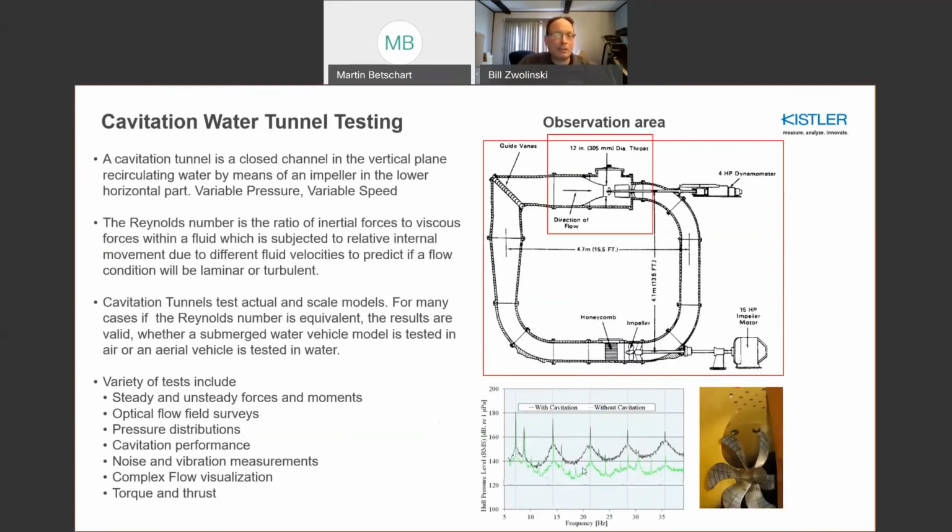Very common technique to look at cavitation, but also with cavitation tunnels, you're also looking at forces and moments. We work with some facilities that instrument dynamometers in this regard, we also look at noise and vibration measurements in the same context. So it's not only just a pressure measurement, but a multitude of measurements going on in a cavitation tunnel.